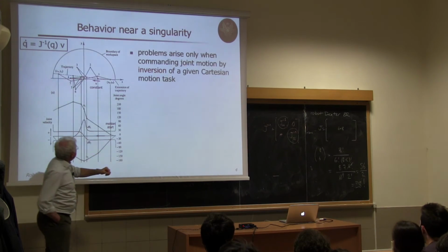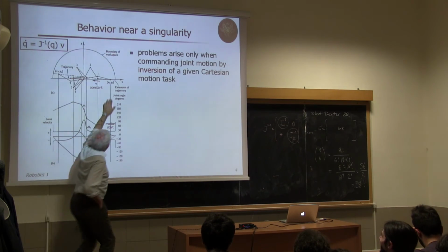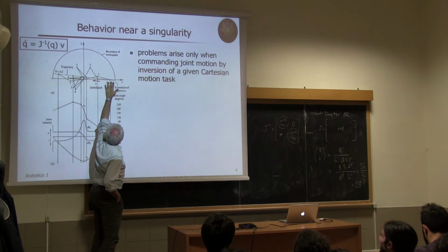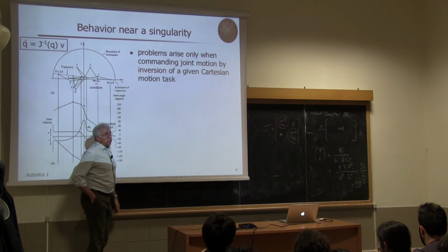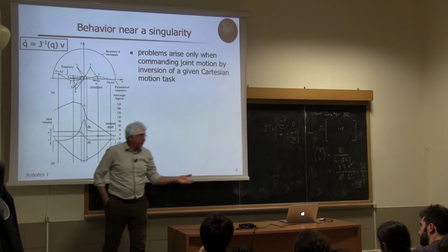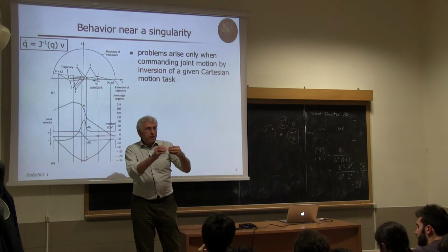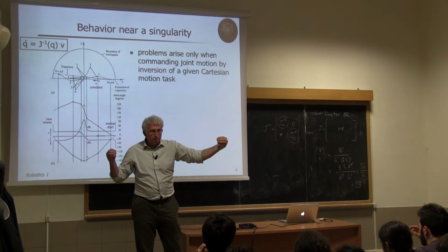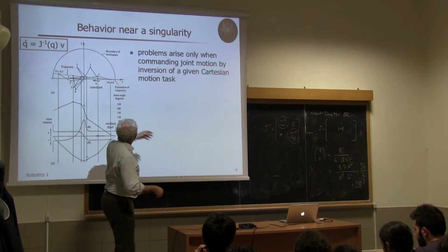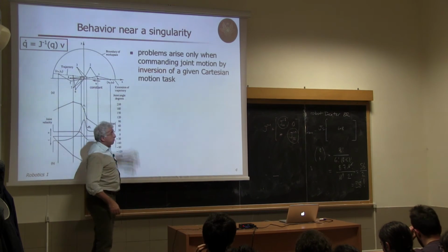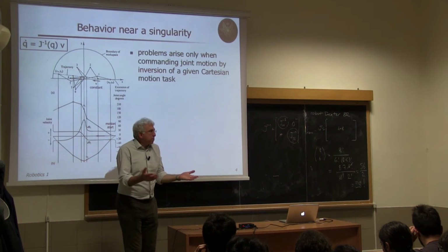And now you assign a motion from this point, x0, y0, along a straight line to the point xn, yn, which is the end of this Cartesian trajectory. Now, this Cartesian trajectory is a linear path that you have to realize with, let's say, constant speed v, so 1 meter per second.